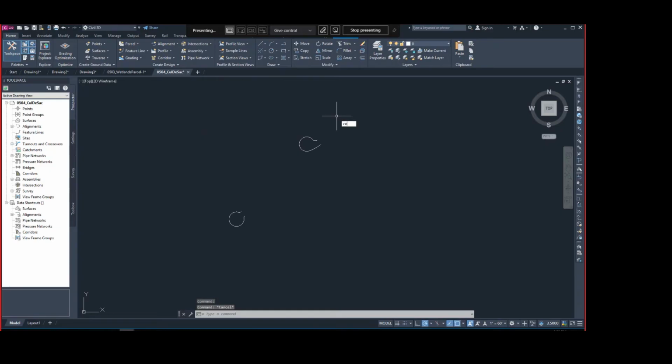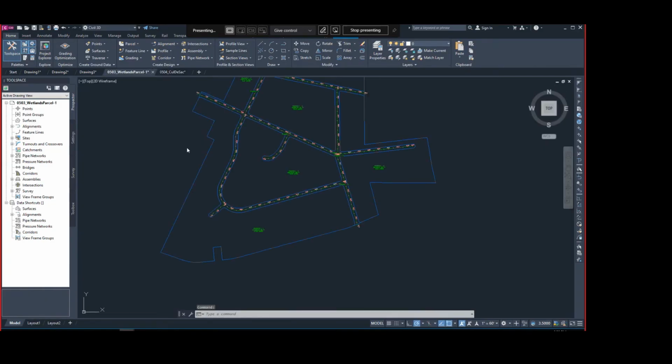So I need to use copy paste: select them, use copy paste, and for specifying base point, type 0, 0, 0, and go to the file and Control V, paste them on 0, 0, 0, exactly here.